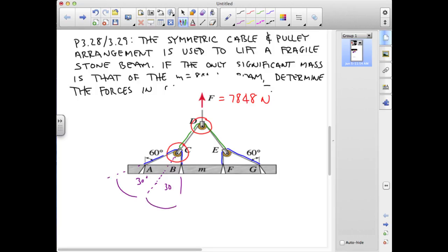And so that in turn means that the angle here is also 30 degrees. Now, having identified that, finding the tensions in these two cable segments becomes very straightforward because you'll remember having established that the cable that comes off the shackle bisects that angle. We don't really need an equilibrium equation normal to that line of action because equilibrium is automatically satisfied there.